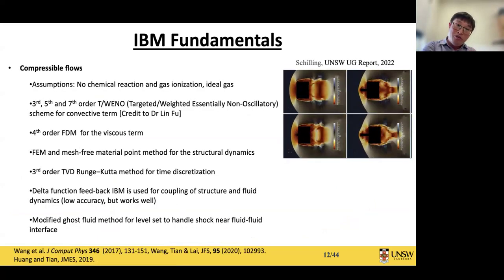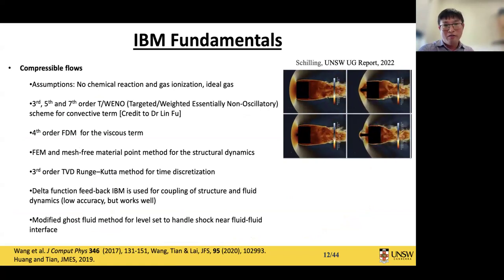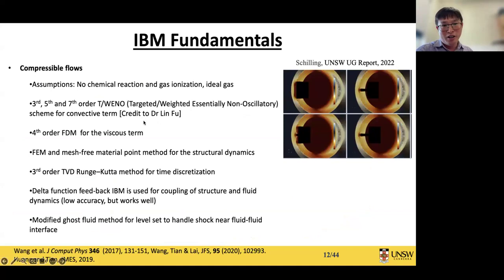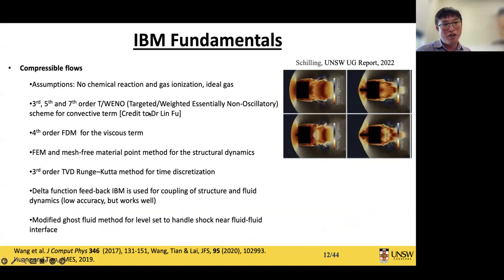And we also introduce similar methods to compressible flows. For example, here we solve the compressible Navier-Stokes equation, and we assume no chemical reaction here. This gas is ideal gas, and we can use high order methods towards the convective term and also viscous term here.